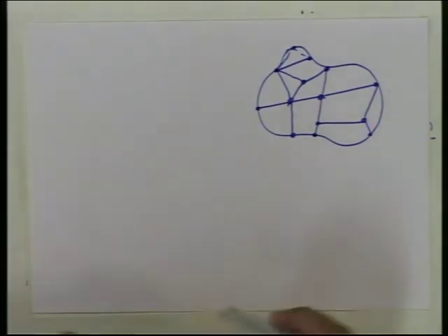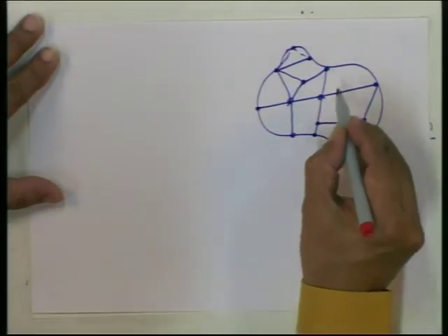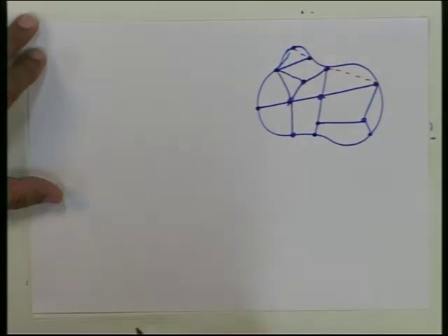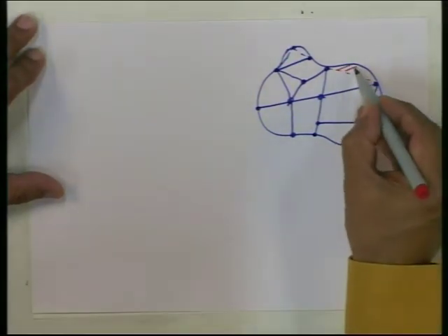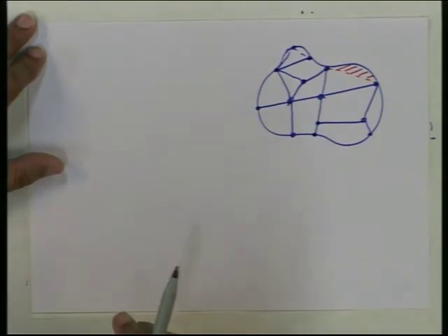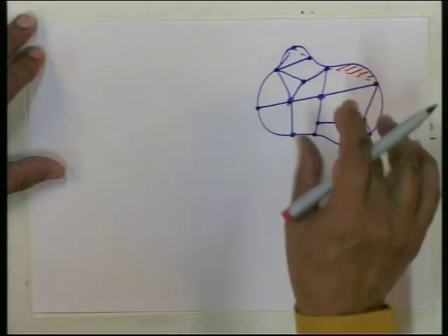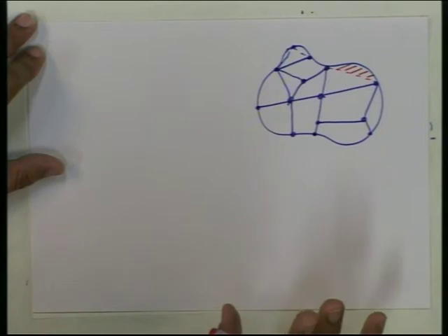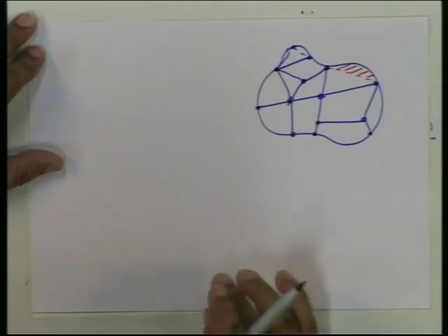If you are using, for example, a triangular element, and this is the geometry, you want to use this big element. So, this one actual geometry will have to be sacrificed. Of course, you make the element smaller and smaller, you can make this red color zone as small as possible, but that must be kept. So, there is always a geometrical approximation.